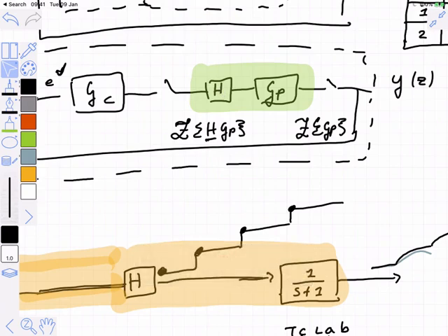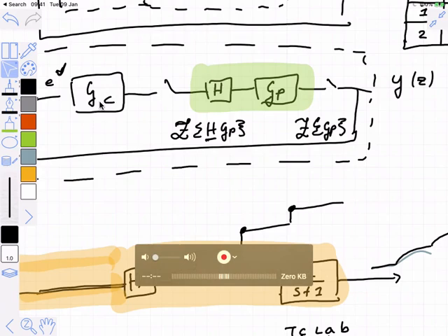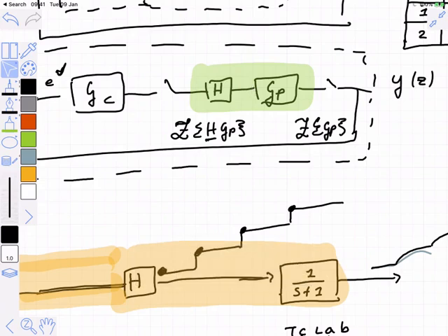In terms of reality, remember that these sampled signals do not actually exist as a signal in time. And so it isn't really possible to interface a discrete system like this with a continuous system without some kind of hold element. There's no equivalent. Discrete signals aren't pulse signals. If you think about something like your TC lab, those discrete signals are literally combinations of bits in the memory of the controller. So there's nowhere in a wire where you could put an oscilloscope.